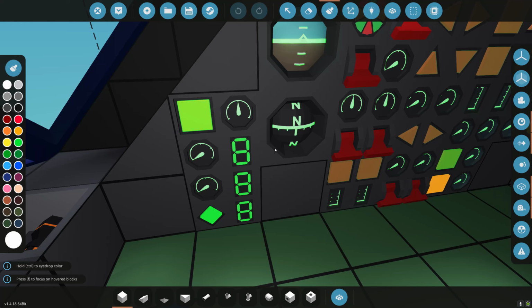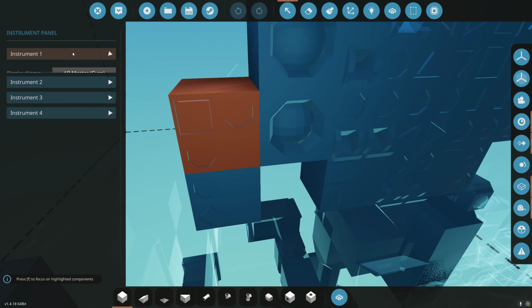If we turned our boat to 090, we would head right to the waypoint. It would tell us it's 20 nautical miles away. If we're doing 10 knots, it would tell us it's going to take 2 hours to get there. This will go off when we're within half a mile of the station.